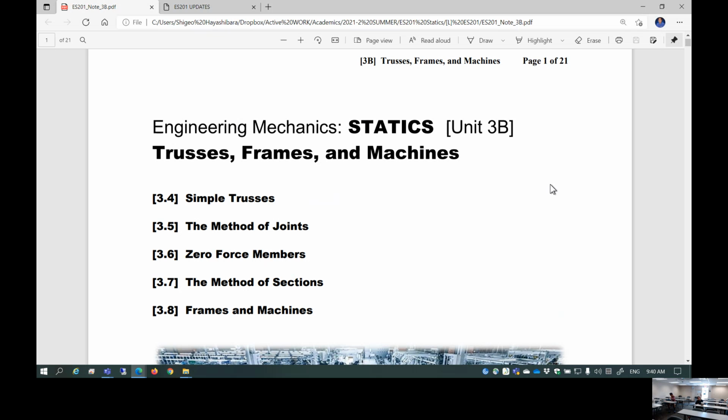It's not difficult, it's just tons of work to figure things out. It's just applying equations of equilibrium at every single joint of the truss frame. If the truss is made up of 200 frames, you have to have 200 equations of equilibrium multiplied, 300 total. If you try to do that by hand, of course, it's going to take time.